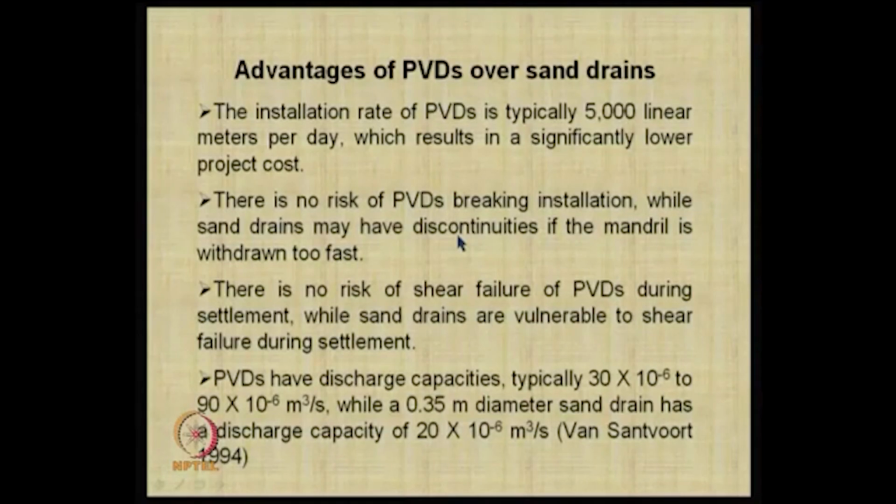So, it may not be as good as compared to this. Number one, the reason is that the shear failure of the PVDs during the settlement is less, whereas sand drains are vulnerable to shear failure during settlement, like there could be some movements and all that. It is not easy in terms of quality control. The other important thing is the PVDs have very high discharge capacities, like you just said.